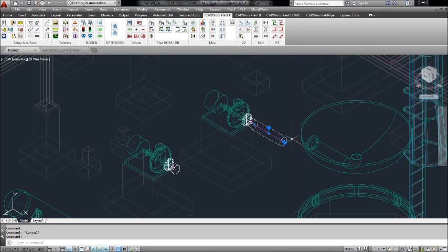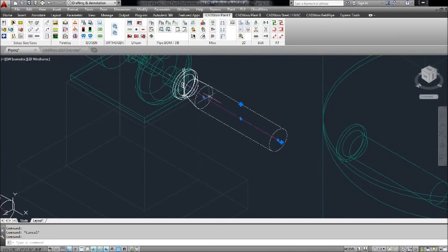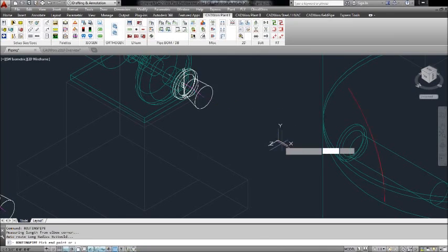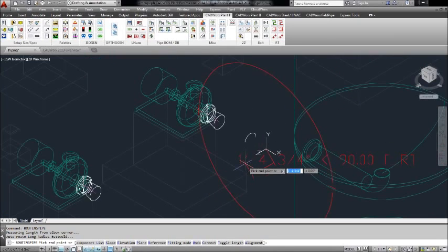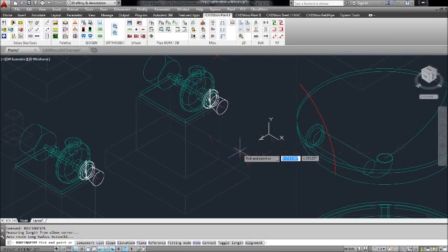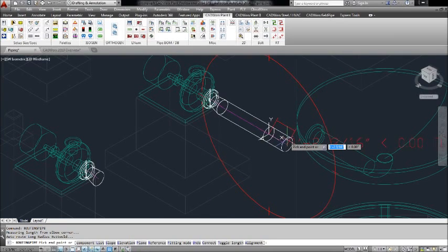Now I'm going to reactivate the plus grip on the end of this pipe. This is another function for our plus grips. Anytime we have a spool piece that's open on the end of pipe, we can hit this plus grip and reactivate the router just as we had left it when we canceled the command. And per my standards here, I put in that 3-foot spool piece. I want to maintain that 3-foot spool piece.